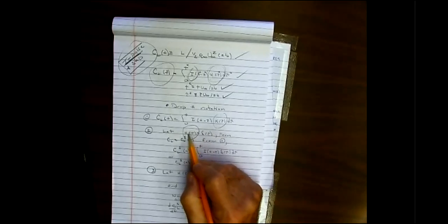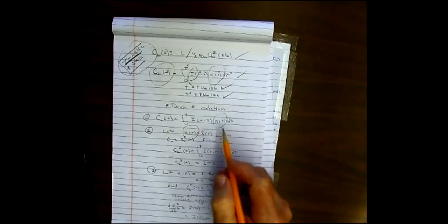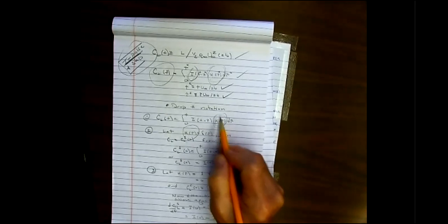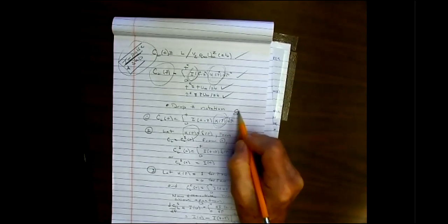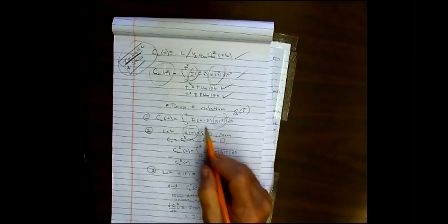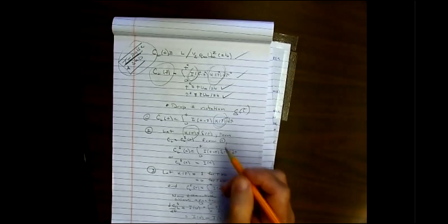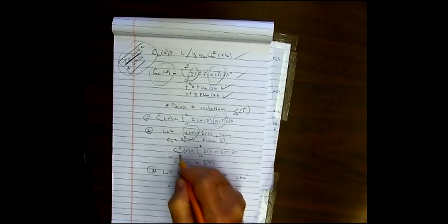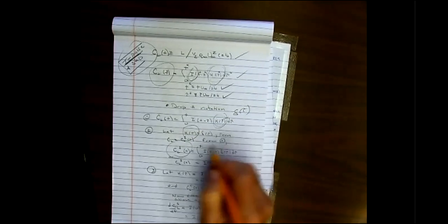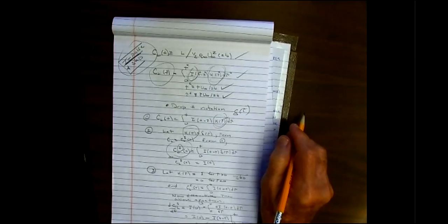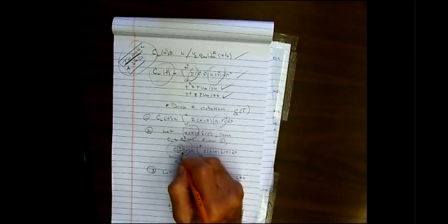So if I let alpha be a delta function, and I put this in this integral, if alpha is now delta of tau, right? Then this integral is just going to become I of t, right? And so the lift coefficient due to a delta function, that's why I put the delta up there to remind myself that this is not any old lift coefficient.